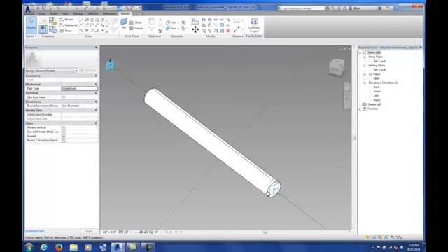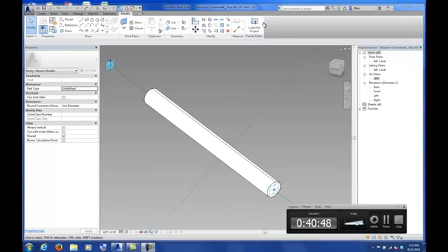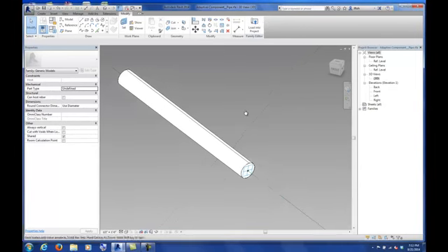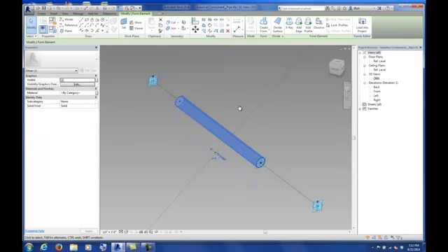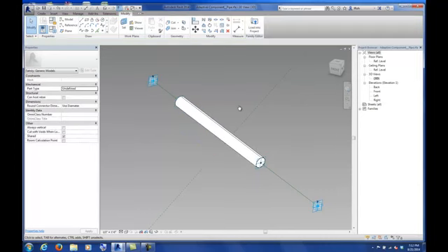Mine is still the 90 degrees, and I couldn't get it to snap the plane. Every single time I did it, it would keep repeating the same action. So now that we have this pipe, essentially this pipe should be whatever the radius that was programmed within that particular family type. I want this pipe to eventually be two different radii. So, sometimes I want it to be the 3-inch diameter and the 6-inch diameter.